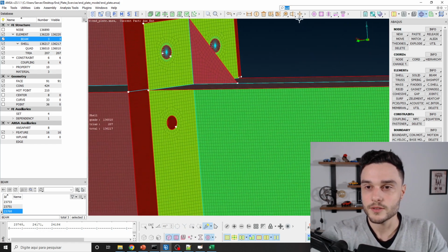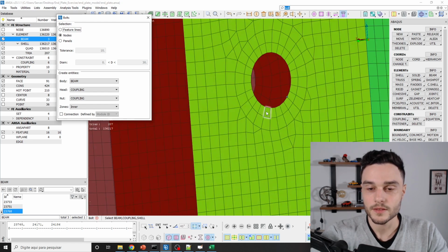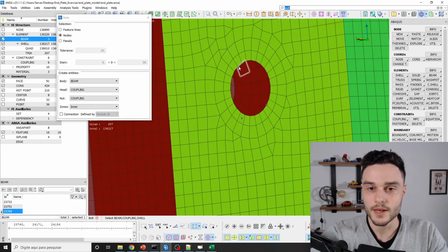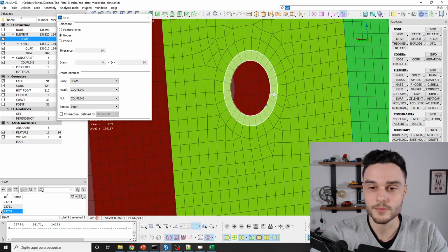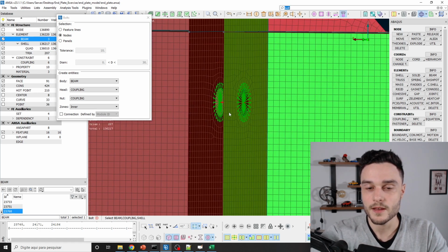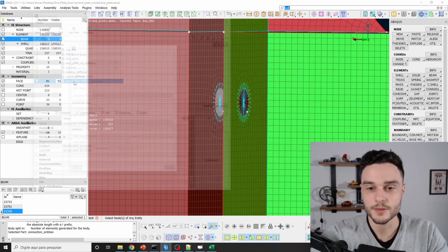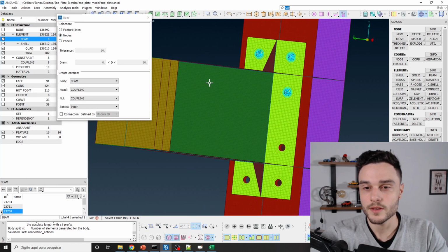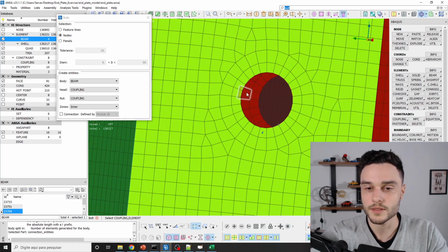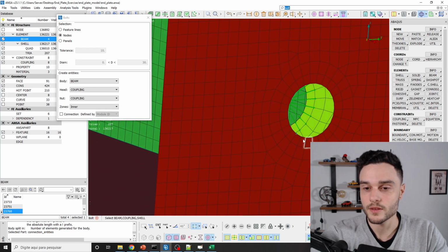All right, so activate bolt. Select 3 elements in this loop, middle mouse button twice, 3 elements in this loop, then middle mouse button twice, and then middle mouse button again and again. Select this part, and then go to the next hole, and let's do this faster now because I think you understood well about it.